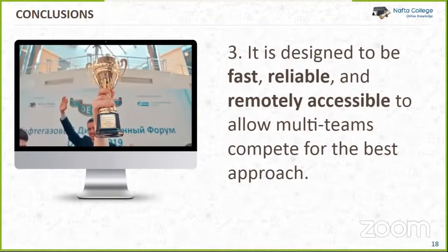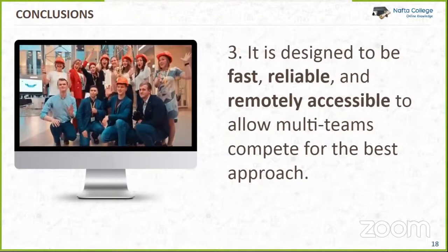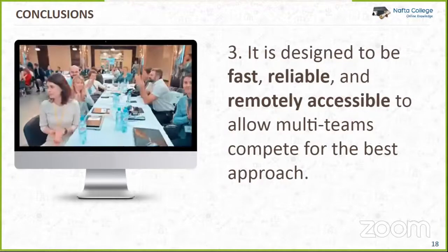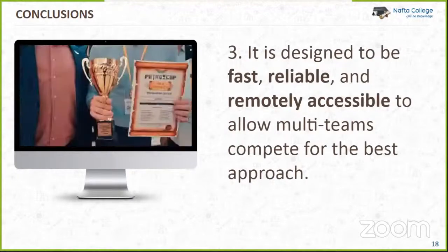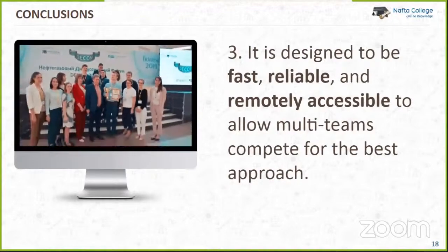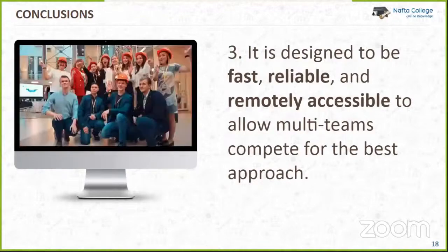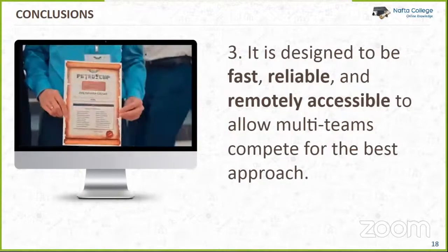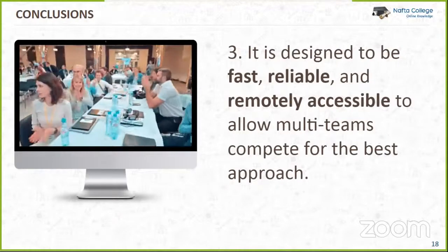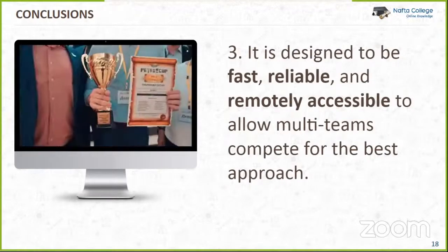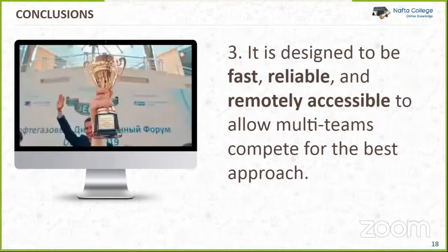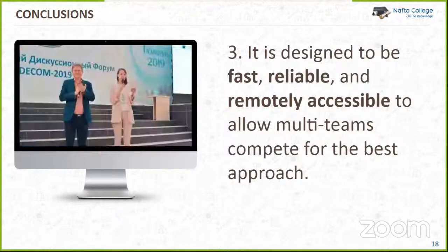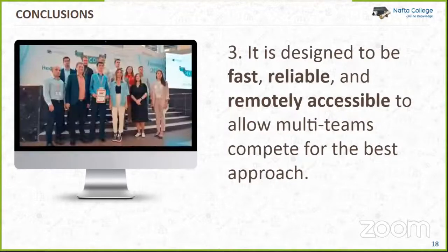I think the value of information is very important. And nowadays, for $100,000, you can get a suite of logs. You can run pressure surveys, interference testing, evaluate the heterogeneity of the reservoir to see if there are any thief zones, some fractures that are taking the water away or causing the water breakthrough. Data is very important. It would allow you to work on facts rather than on humming and hawing around it.